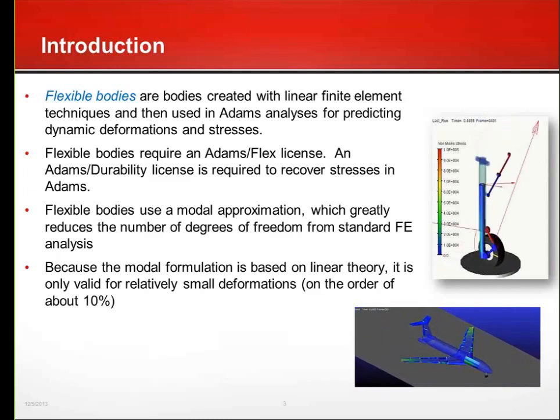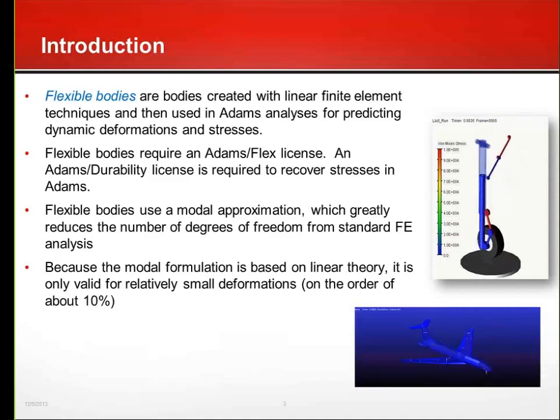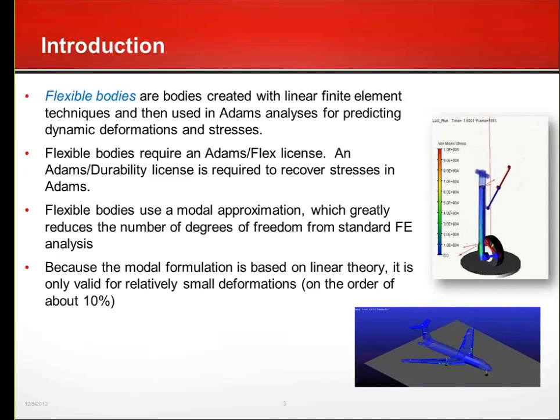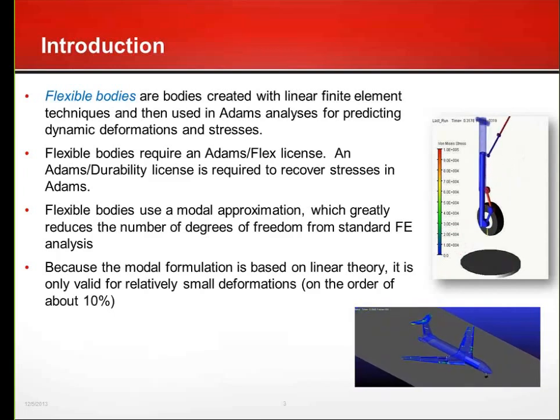To do this, it requires, at a minimum, an Adams Flex license. So that includes both solver components and user interface components. And also an Adams Durability license is required to recover stresses in Adams. So the basic Flex license just gives deformations.